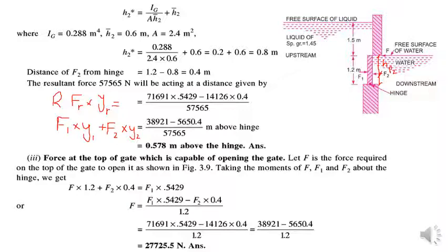Net force is with us, so you can have this equation. On the left hand side you have the resultant force multiplied by the distance, and this distance may be yr, the moment arm of the resultant force. This will be equal to the moment produced by the individual force F1 multiplied by its moment arm, and the second force F2 multiplied by its moment arm.